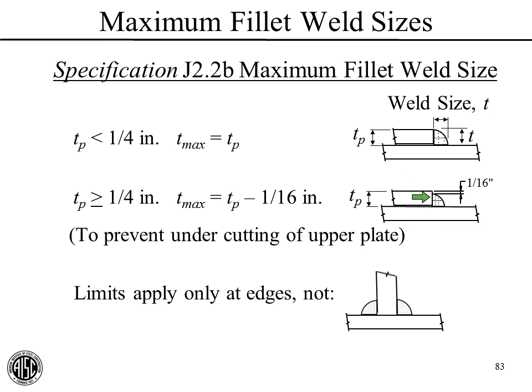You can't tell where the weld is starting and ending. So you may have a weld that looks like it's based on the apparent edge, or the apparent corner that's left. It may be that the weld looks like it has a larger effective throat than it does. It may not have the effective throat that we use in design. So we want to hold this down 1/16 of an inch to leave this corner intact.